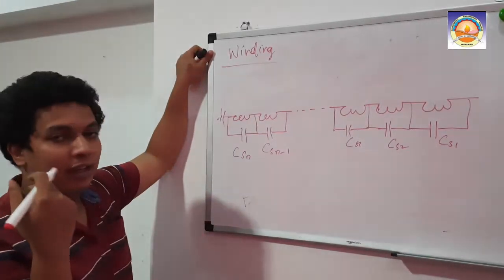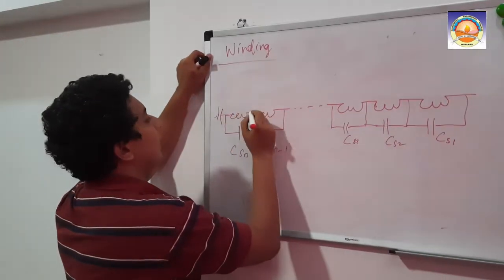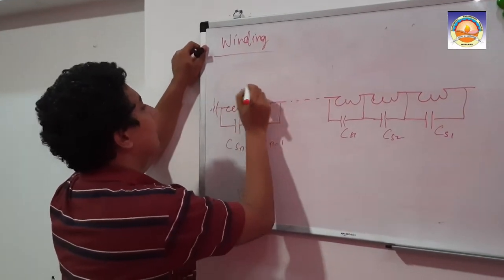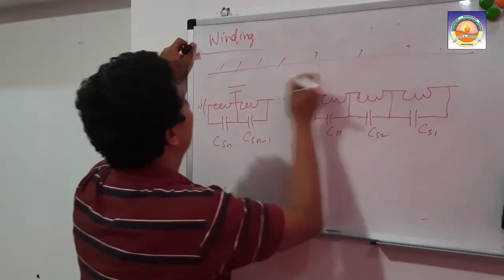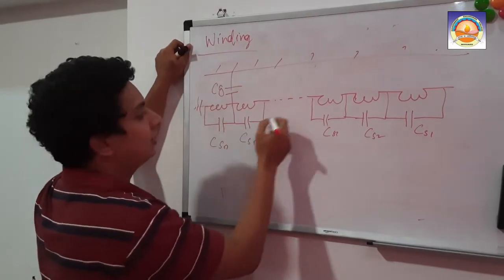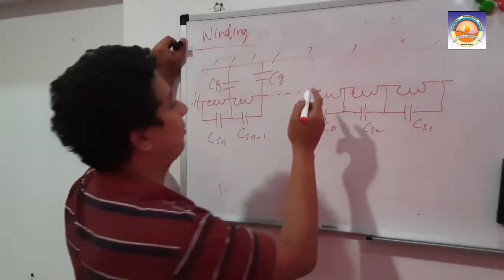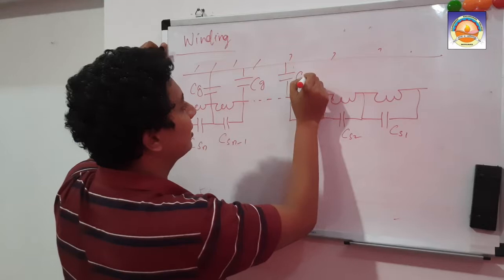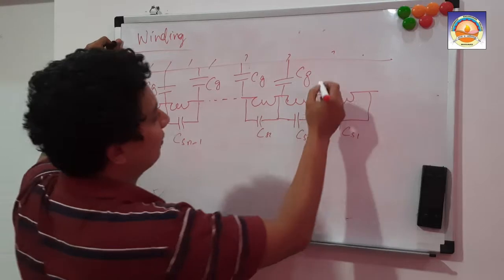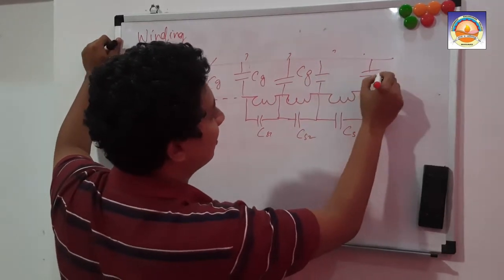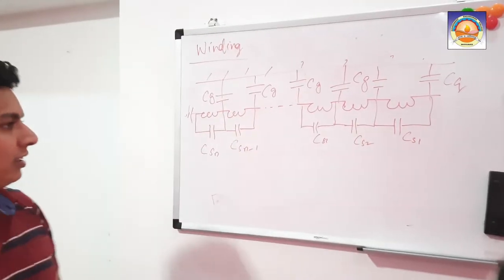Another kind of capacitance that we are dealing with, it will be this way, like what? Like we have with respect to ground, let me say. So this is called CG, with respect to what? LV and SP winding. We are considering only the half portion of the winding, so this is how we represent it. This is CG, with respect to ground, the capacitance between LV and SP windings. This CG value will be marked as constant and CS is differing. We will see the explanation later.